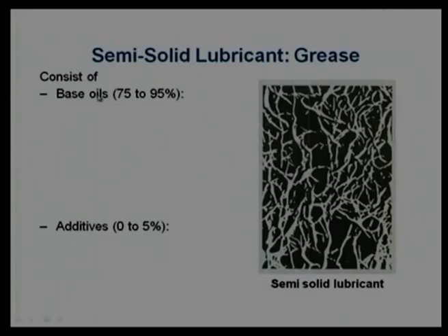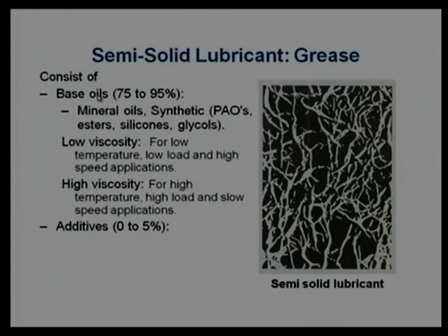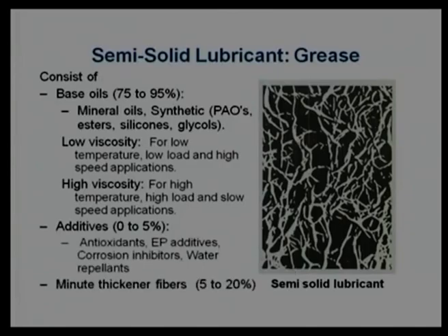That is why I say that it consists of the base oil as well as additives and thickener, and this is what we are showing here, the thickener. This thickener makes the structure in such a manner that liquid cannot easily escape from that integrated part, or maybe we can assume that it acts as a sponge, and a sponge has a capability to retain the lubricant within it.